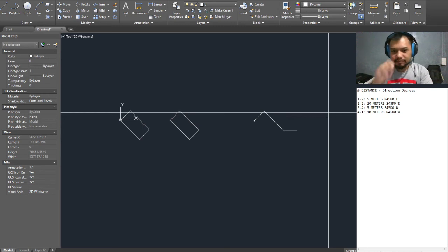Angle symbol, we're going to do the math again. So 90, 180, 180 plus 45 equals 225 degrees. And finally, the last line, at 10,000, and we're going to say angle symbol 135 degrees. Or you can also press close again to make sure that it's one solid object. So we can undo that, press close. Keep in mind that you can also use the minus symbol. As you can see, we went up 45 degrees. Then we can also go back negative 45 degrees, then negative 135, and so forth.